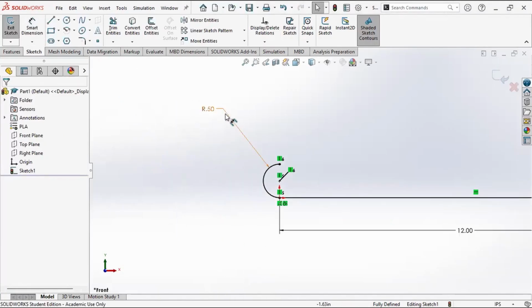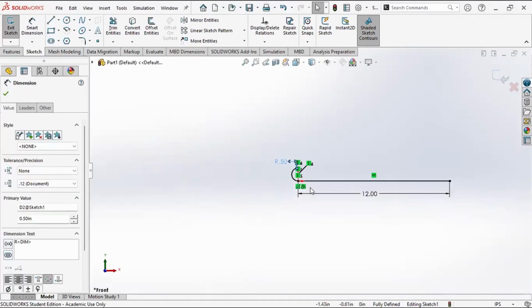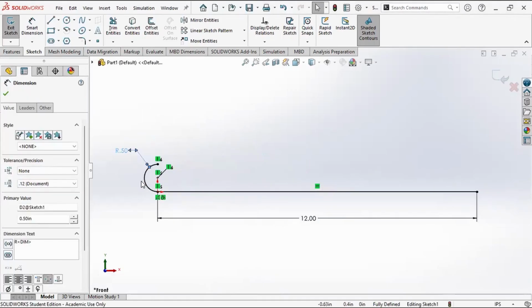Right? Notice now it shrunk significantly, but we now have a radius. We have an arc there on the end of our line. Now we could close this in and do more sketching of this nature, but this is the key to constrained sketches: we want to make sure that those points can't move, and SolidWorks gives us a good double check by turning things black for us.